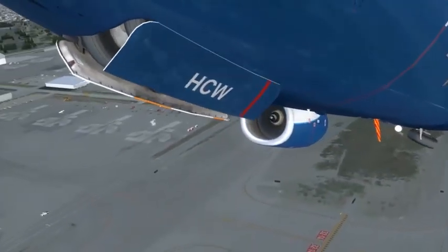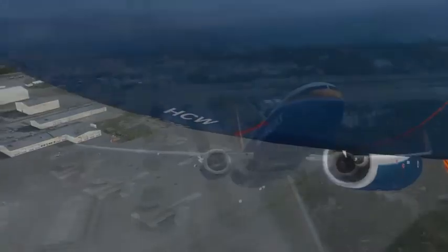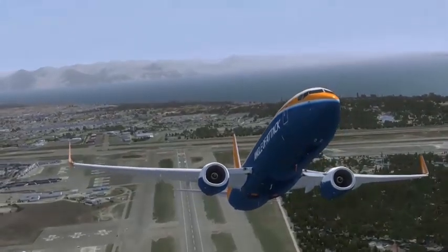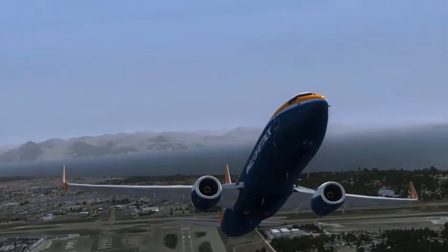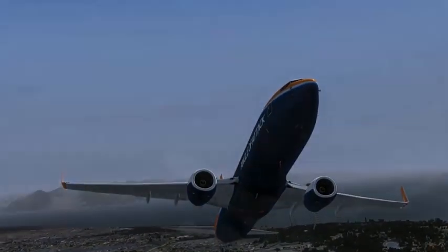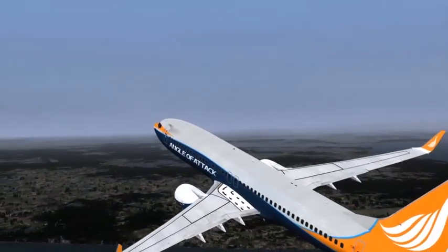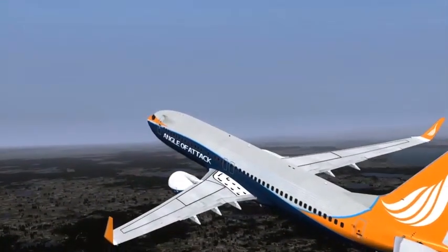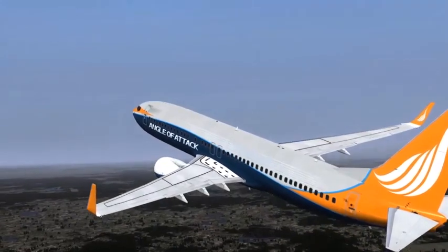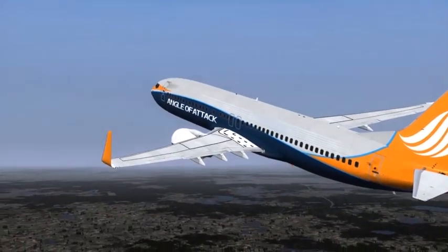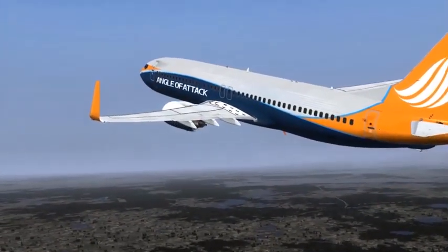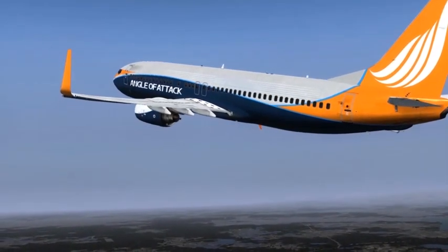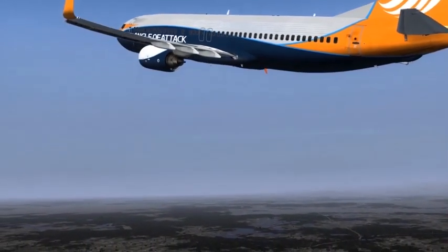During the takeoff phase, the cabin is pressurized to 0.1 psi below field elevation by slowly closing the outflow valve. The reason for this is to prevent an uncomfortable pressure bump for passengers when the airplane rotates. Also during the takeoff phase, the cabin altitude rate of change is in the order of 350 feet per minute.